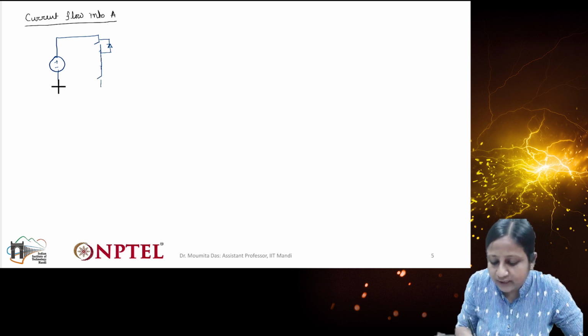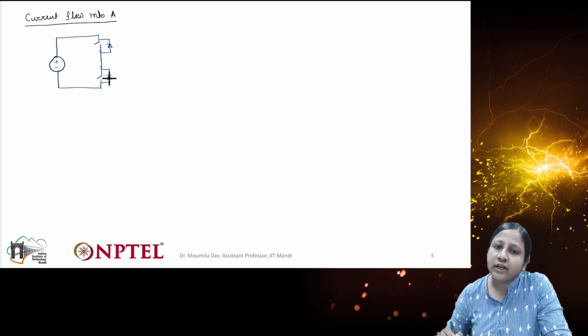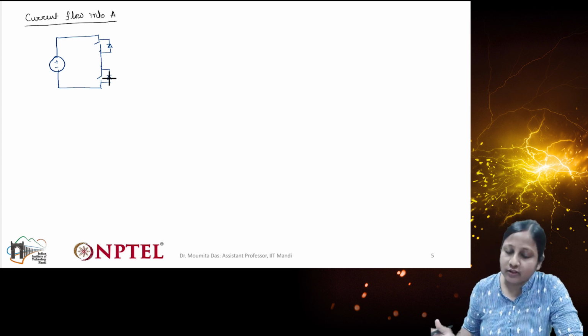Now for silicon, some of the devices may have a reverse recovery problem with respect to the body diode of the particular switch. Then we can either connect a separate diode, any Schottky diode, or use the body diode of any switch which has a faster body diode for this test.